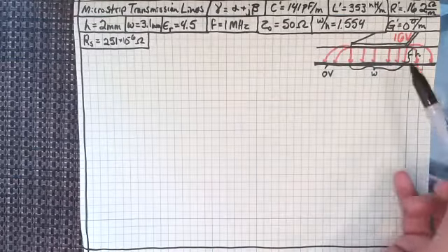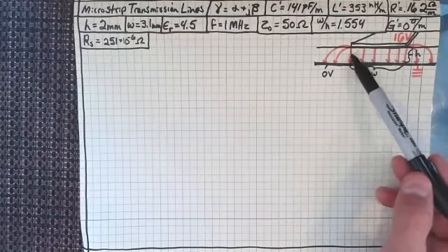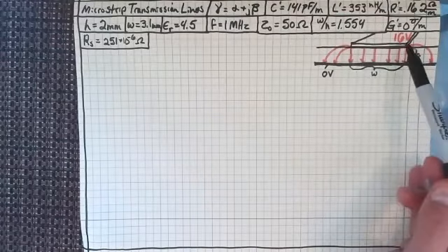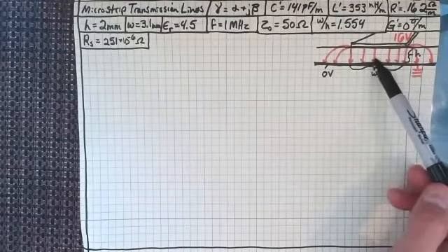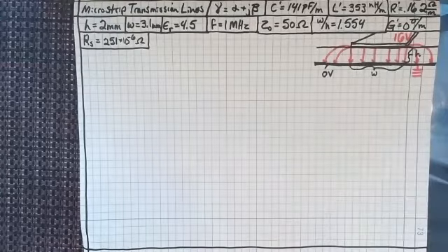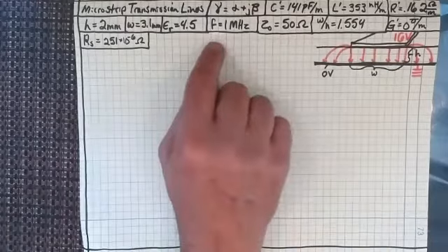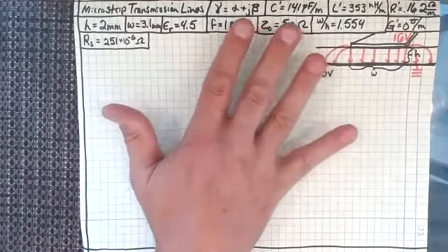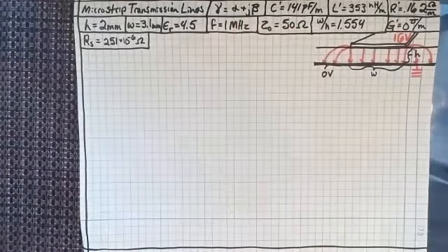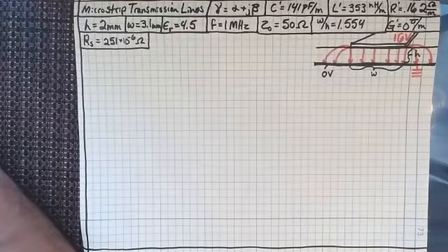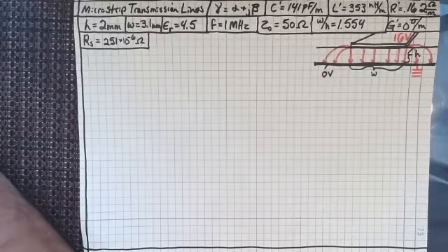I made an assumption: for microstrip transmission lines working over the distance of your phone's printed circuit board, which are obviously very short, we can use the lossless line approximation when we've got very short connections or very low frequencies.